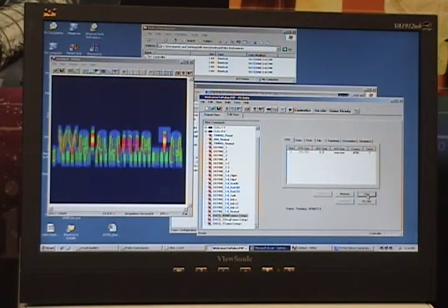We can have up to 512 megabytes of acquisition memory per card, and we can stack up to 8 acquisition cards in a system to provide up to 4 gigabytes of uninterruptible acquisition memory. This sample pattern is 256 by 256, and we store 2 bytes per pixel, so we can collect up to 4,096 contiguous frames of data into this single 512 megabyte card.